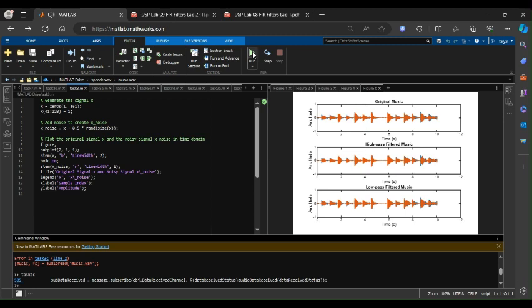The high pass filter attenuates frequencies below 500 Hz, while the low pass filter attenuates frequencies above 10,000 Hz. The original music signal and both filtered versions are plotted and played back sequentially to demonstrate the effect of the filtering process on the audio signal. Adjustments to the filter parameters and plot limits can be made for specific audio processing needs.